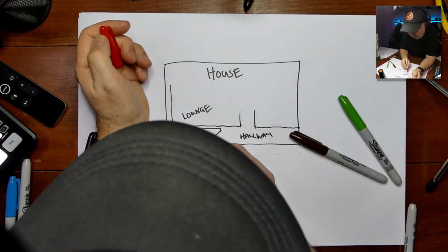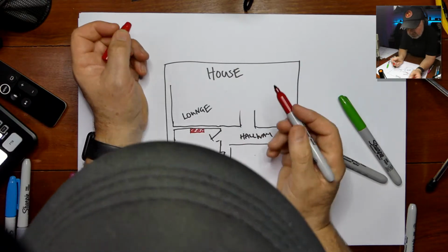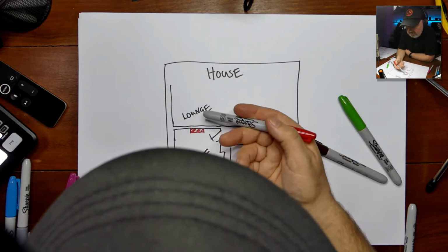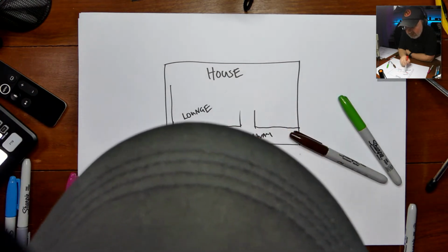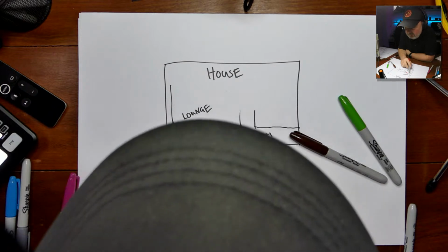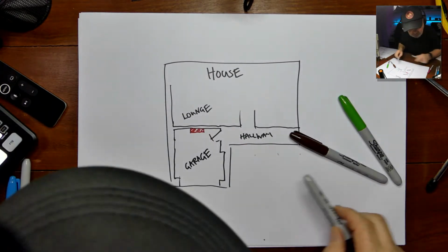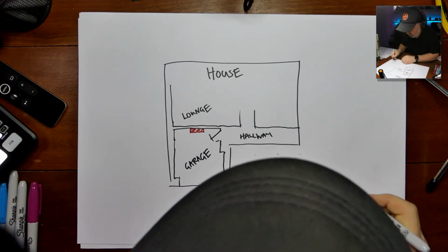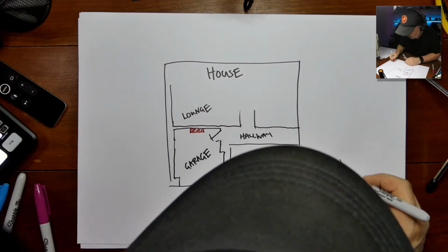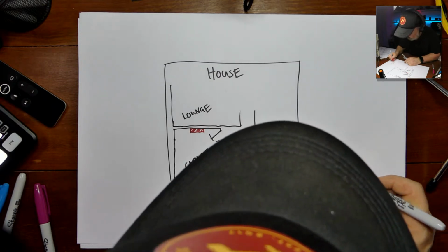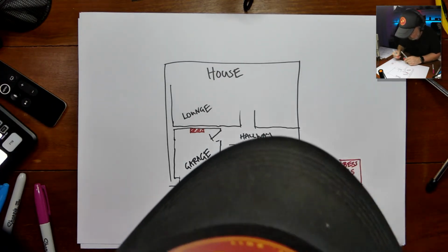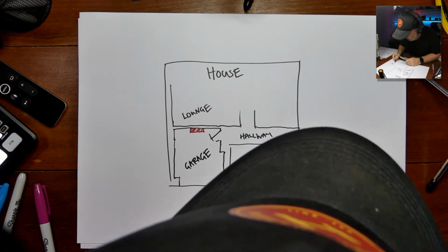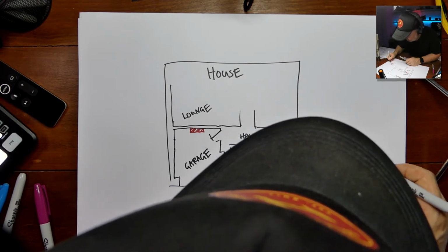Can we put it here? Yes, we can. We can put a Section 4 and a Section 5 battery adjacent to a wall that has a habitable room behind it. But, and there's a couple of buts, that wall now has to have a barrier for the protection against the spread of fire. And the barrier needs to extend 600 either side and 900 above. So just in plan view, if I draw that over the side here, if my battery system is this big, that's my battery system, or BESS, so it could be a BESS or a battery system. I have this requirement to have 600 and 900 above. Protection against the spread of fire. So that's 900 and that's 600 here.